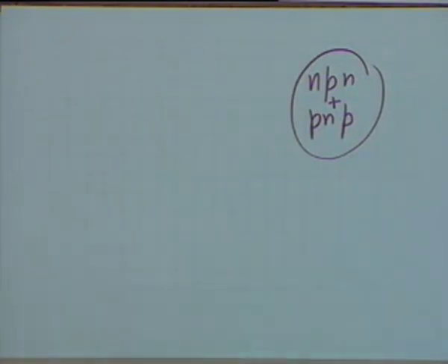By making a combination of two such transistors, instead of using two NPN or two PNP in a class B push pull amplifier, if you make a combination of NPN and PNP, then you can avoid the transformer. Let me draw this circuit first, then I will explain.